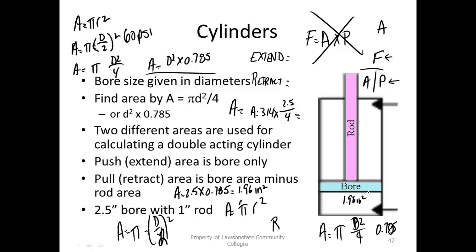And so anytime the fluid comes in on this side, we would push that way. And then to push it the other way, we would exhaust it. By the way, the name of this is hydraulics pneumatics. What you're going to see is, most of the time, if that arrowhead is filled in, it means we're dealing with hydraulics. If it's not filled in, it means we're dealing with pneumatics. And the cylinders are basically the same.